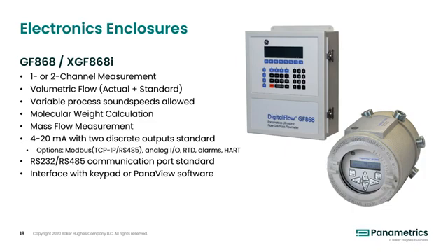Both electronics allow for either single or dual channel flow measurement. They come standard with volumetric flow, molecular weight, and mass flow calculations as we discussed earlier. In addition, both flow meters have a serial communication port standard to allow for laptop communications with our PanaView software.